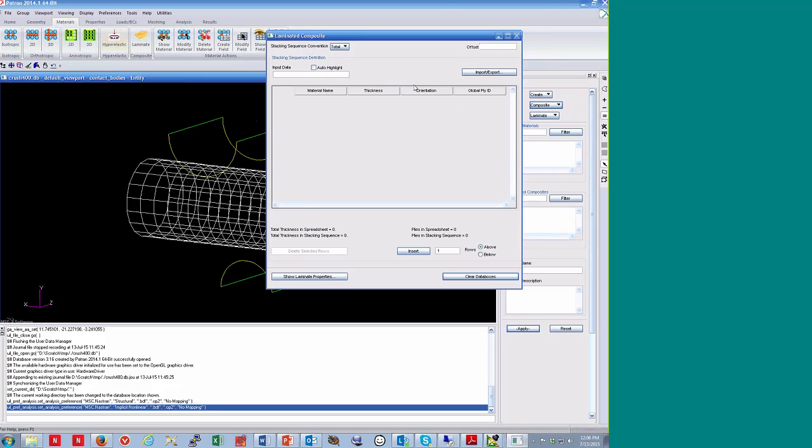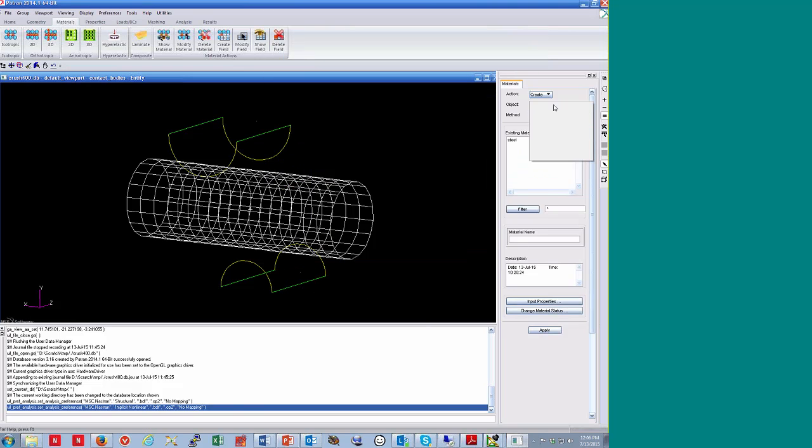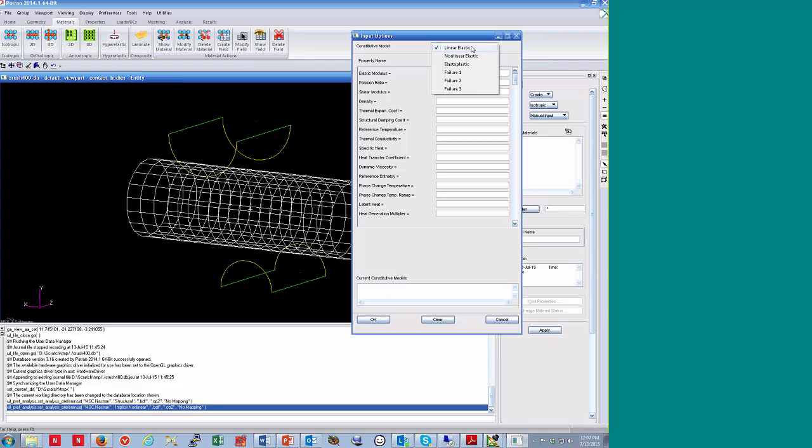So go to the materials application, and under here you'll see we support the standard isotropic, orthotropic, composite. One thing that's different is that we now have hyperelastic here as the main menu, because hyperelastic is a primary Nastran material, so we want it to be up front in this list. Under each one of these, you would define different constitutive models, be it linear elastic or nonlinear elastoplastic. All of this input is now specific to setting up particular cards in Nastran.